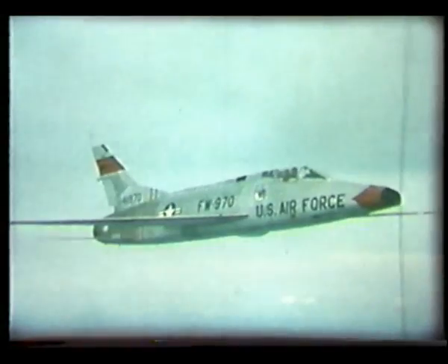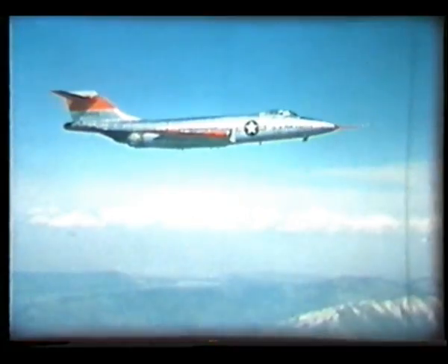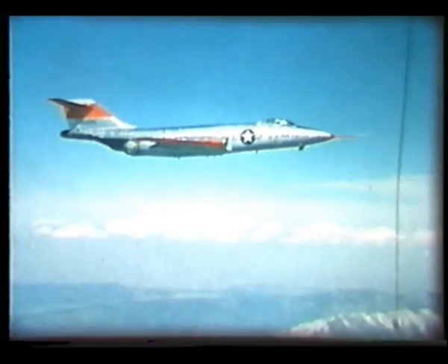Above Mach 1, the bow wave adds its own drag. This can be reduced by having leading edges, nose, sharp rather than rounded. Compare the effect on the bow wave of sharp and rounded leading edges.